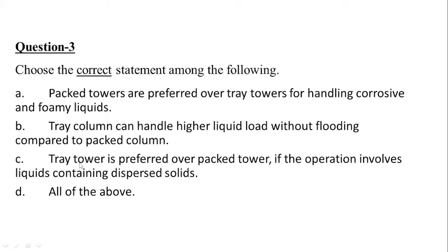If they clog in the pores of the packed bed, then there will be increase in the pressure drop between the inlet and the outlet of the packed tower. This will lead to excess load on the upstream pumps and compressors.